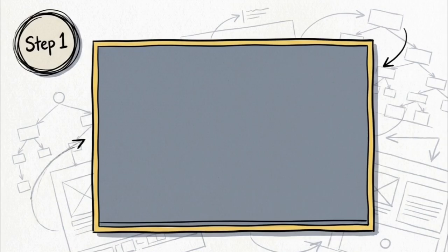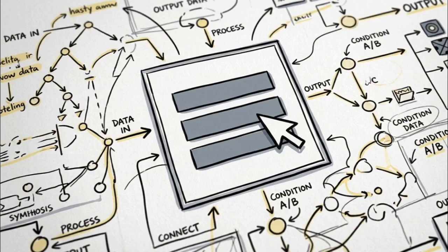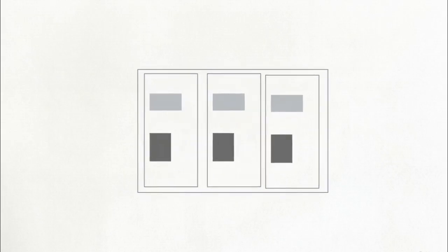Here in Step 1, we start with a blank canvas. The immediate objective is to drag three disparate metrics, like sales, quantity, and cost, and drop them into one centralized visual block. The format hierarchy lets you instantly restructure that block into a stacked vertical column, a horizontal row, or a compact grid. Notice how the entire block updates simultaneously. Establish your global design style first using Apply to All, and only override individual cards afterward.